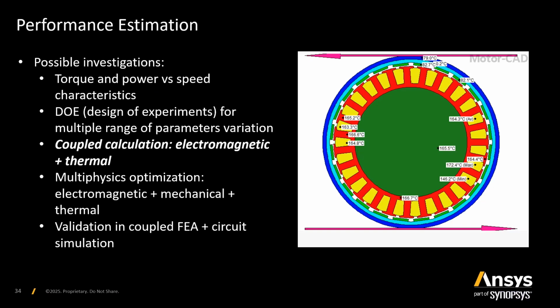A big role is played by the aluminum axle in the middle of the stator, which works like a heat sink for these machines. While the rotor, you'll notice, is quite happy on the outer of the stator, with temperatures around 80 to 82 degrees Celsius.